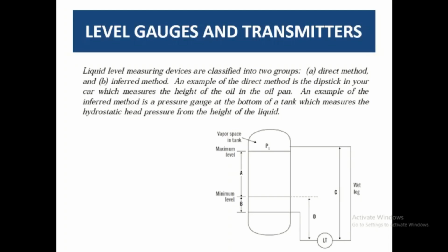Similarly here, from the formula P = rho g h, which we studied a lot in fluid mechanics, the pressure of a liquid column is directly influenced by the height and does not include any impact of the diameter. So that theme can be used: if you are using pressure measuring devices, that value can be inferred into liquid level. This is the second method, the inferred method.